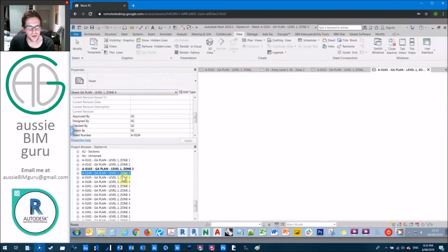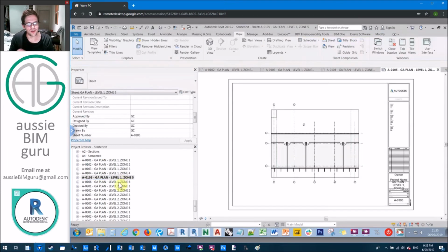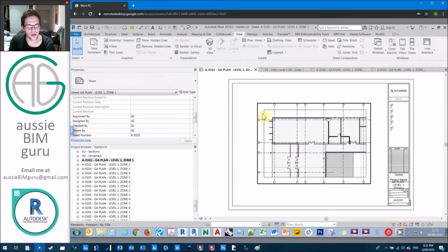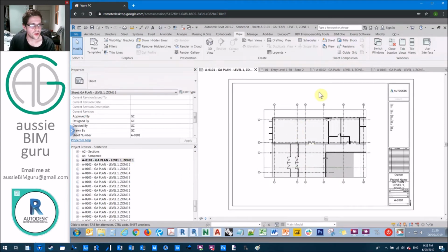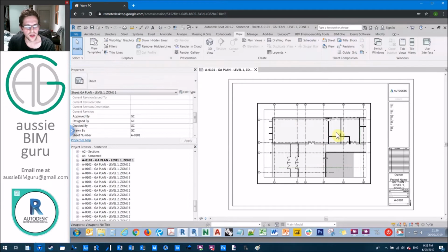And you can see that they're being placed in pretty much the same spot. They're all being centered by Dynamo. So the last thing we need to do with our views, now that they're on scope boxes, well, actually two things. The first thing we're going to do is set up what's called a view reference. Not a lot of people know about view references, but they're quite handy.